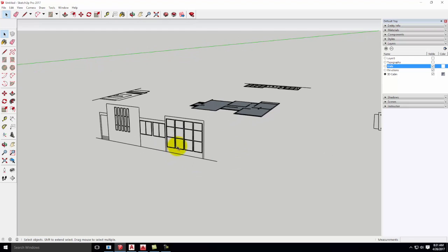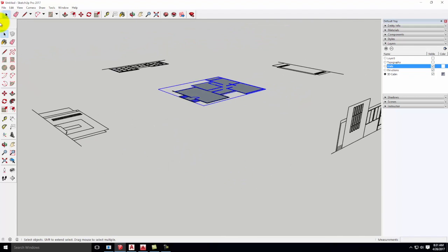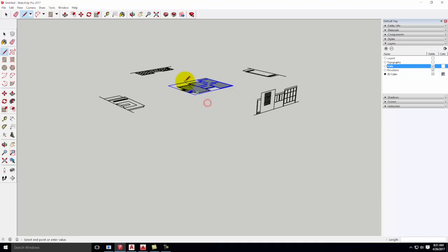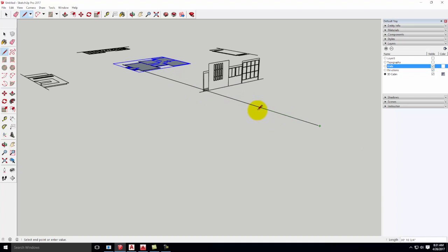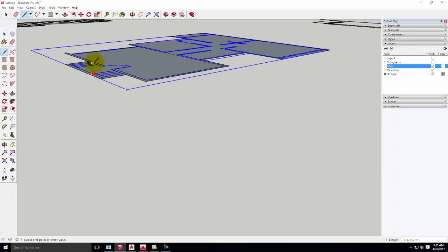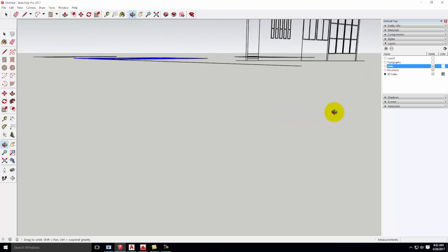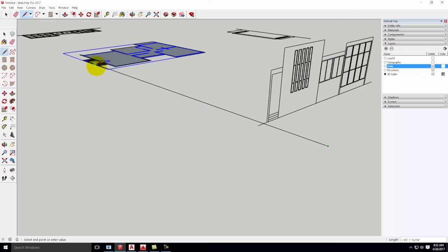Now I need to make sure that this lines up with my floor plan at the correct plane. So I know that the floor in my particular building lines up to this level right here, or the bottom of these windows, because these are floor-to-ceiling windows. So I'll draw a line from here out along the green axis. So you see how when I drew that line, I waited until it was green before I clicked OK. When I do that, it now gives me what level that is.